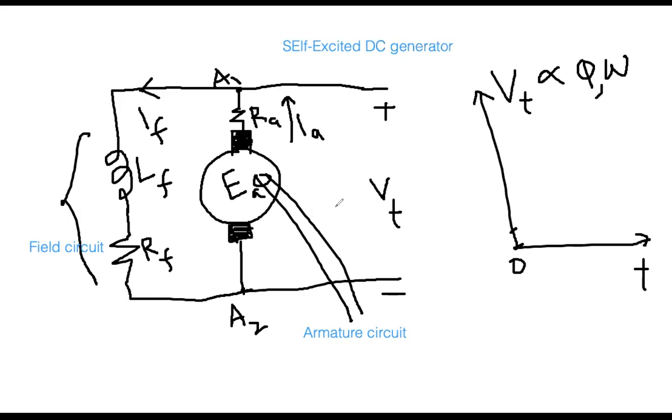Say you got 2 volt at the first moment: you make this connection, take a voltmeter here, and notice 2 volt. That is great. This means there is some remaining flux. As you keep conducting experiments, voltage gradually builds up, field current flows, and it gets gradually excited. Next time the voltage will start increasing. It will go in that way.